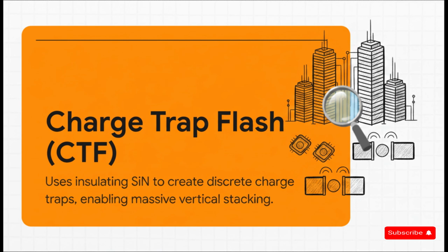It was a mess. The brilliant solution was charge trap flash, or CTF. Instead of a conductive layer where the charge moves around freely, CTF uses insulating silicon nitride to create discrete, localized charge traps. Because the charge is trapped and can't freely flow, it doesn't leak over to its neighbors. And that right there is the secret sauce that enables this massive vertical stacking.